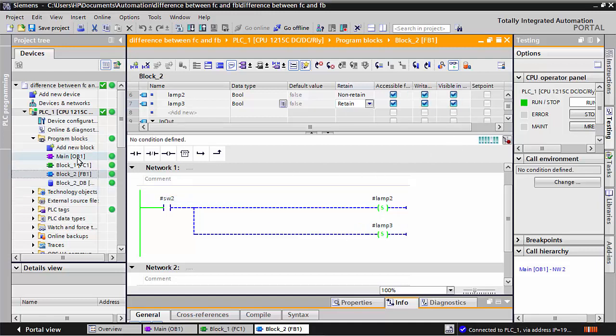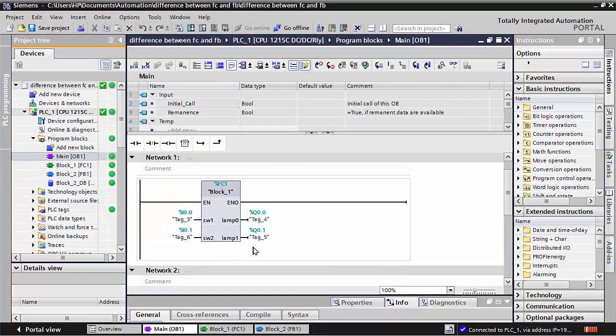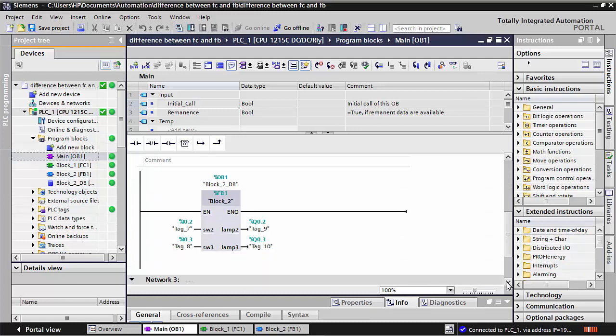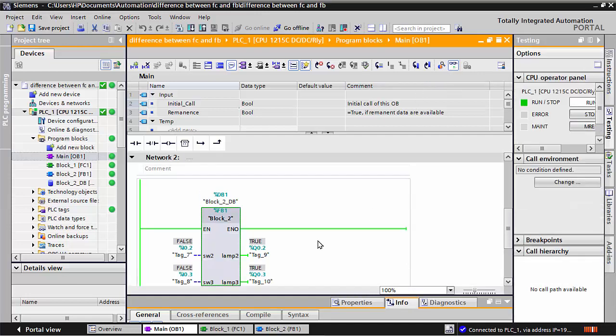Also we can go into the function block main, we can see it also. Here, this function block, and this is our FB1. Go online and see, Q0.2 and Q0.3 are now on, but my I0.0 signal is now off. This goes into set condition.